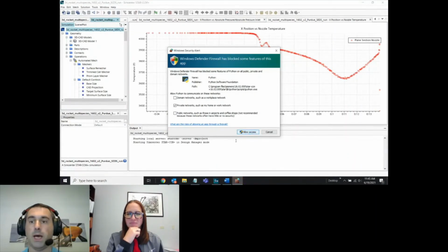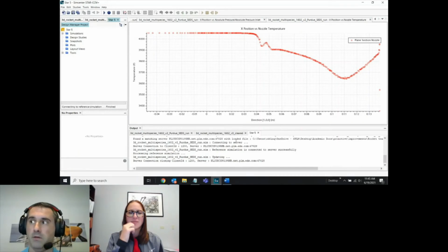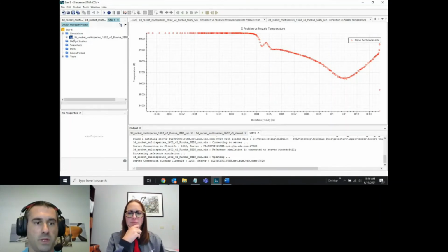So you can tell it, I want the numerical data of drag, I want the numerical data of thrust, and those are just numbers it spits out. But then you can also say, I want to look at the plot of the nozzle pressure per position. You can say, I want to look at the result scene, and then just make sure that you turn on or off whatever you want beforehand. But you kind of just come through this and set that up to do that kind of thing.